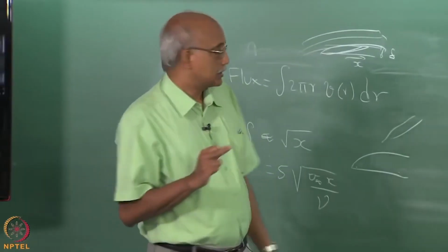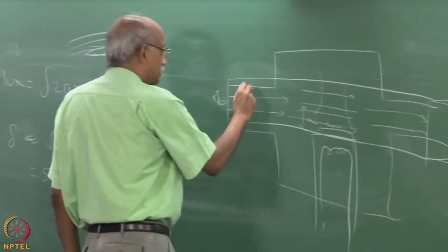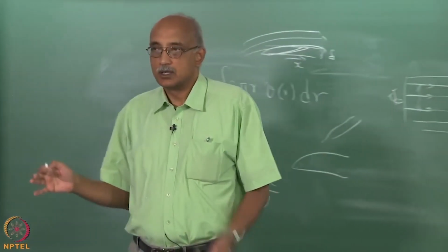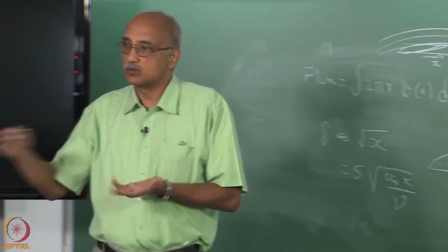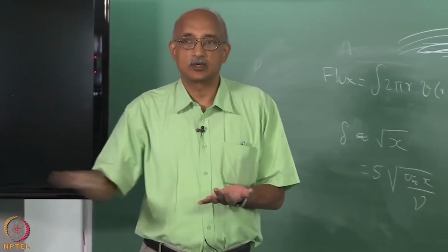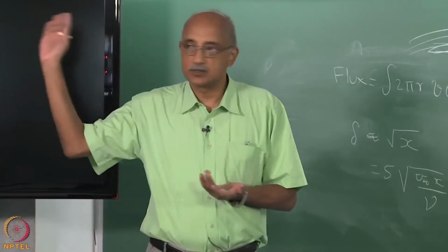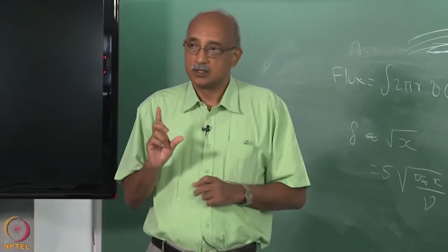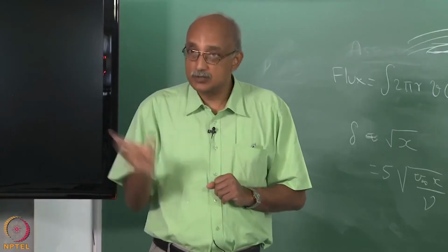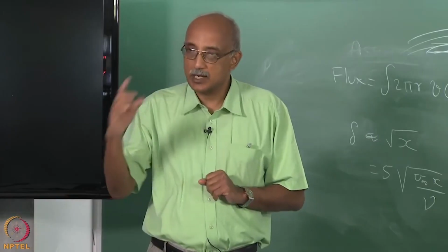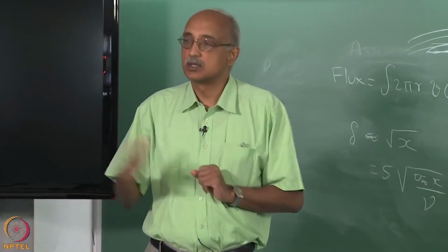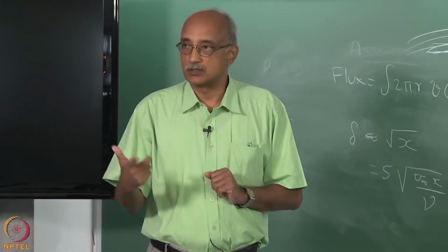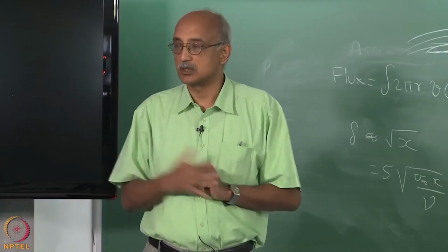See, the thing you have to remember is material is distributed in this direction, right? It is distributed among all the streamlines that are flowing. If the entire flow occurs in a plug flow, then only the bottommost layer of the fluid will ever come in contact with the substrate. The rest of the material will just go by, so that is not the right way to do it. In fact, the transition to a uniform flow, which is still a mixed flow, is a key thing. You want to have a mixed flow condition before the fluid encounters the substrate, but at the same time you do not want turbulent mixing, you essentially want a laminar mixing to occur.